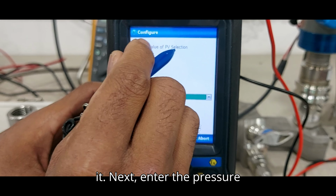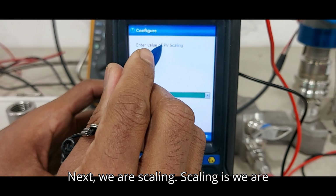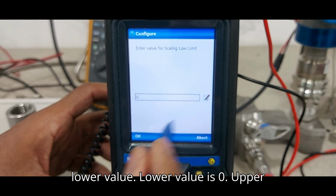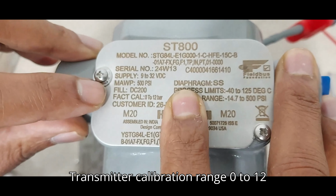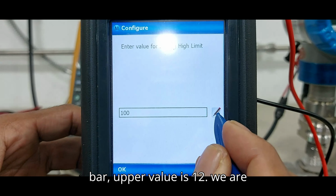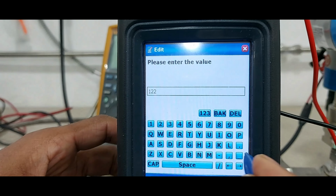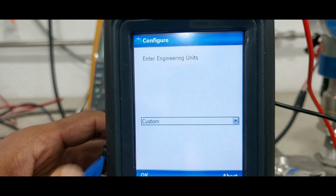Next enter the pressure, PV value selection is pressure. Next, for scaling we normally use linear for a pressure transmitter. Next enter the lower value 0, upper value. The transmitter calibration range is 0 to 12 bar, so the upper value is 12. We select this arrow and enter 12 bar, 12, then OK, then OK.